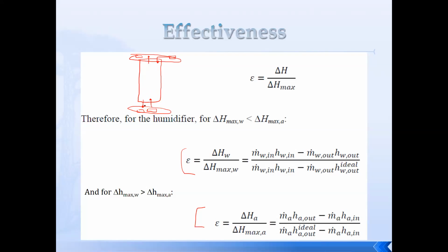So at that state, what we need to do is probably follow how the air is going to be humidified and heated, how the water will be heated and humidified, and look at the smallest difference between them and call it the enthalpy pinch. So that's a new definition that we have just worked out in the last period of time. We had a couple of applications that appeared this year talking about how the enthalpy pinch can be calculated and how it can be integrated into the effectiveness equation.